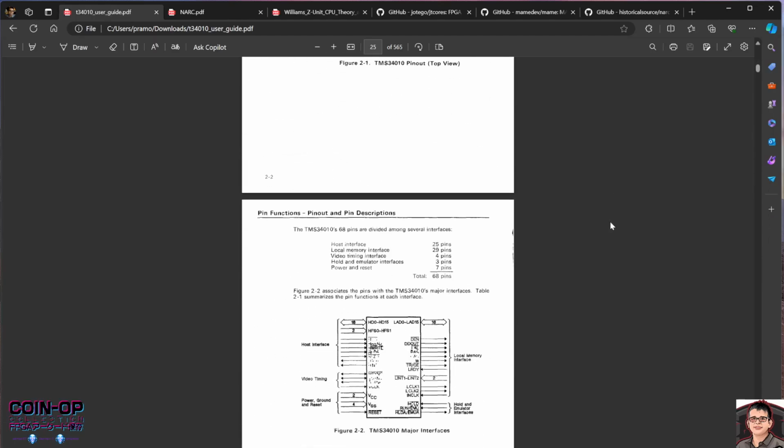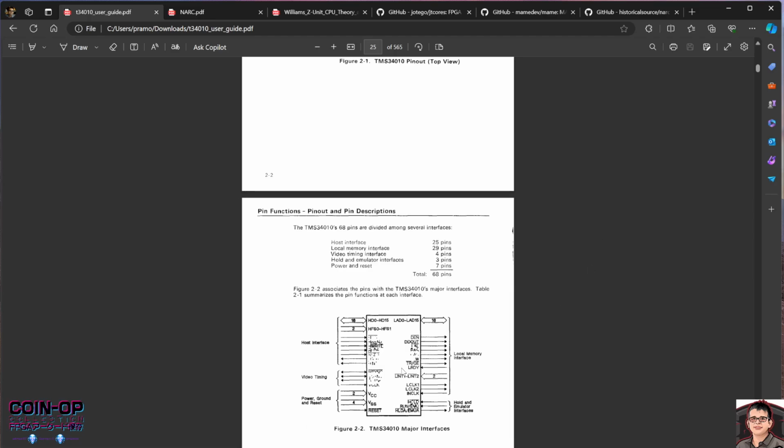And what I try to do is I take a look at the pinout first of all, see how the pinout helps, because the pinout tells you how the CPU or that component, this is not only for CPU, it's for different component chips, how the chip interfaces with the outside world. Because a lot of the time, the question is not what does a specific chip do, but rather how does that chip communicate and work with other chips on the board.